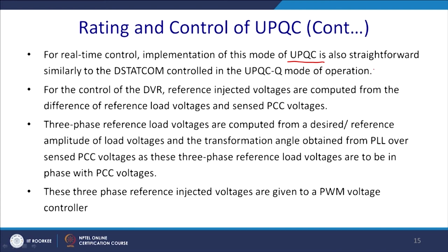For this control, the DVR reference injected voltages are computed from the reference load voltage and the sensed PCC voltage, and it can only correct the sag, mind it.